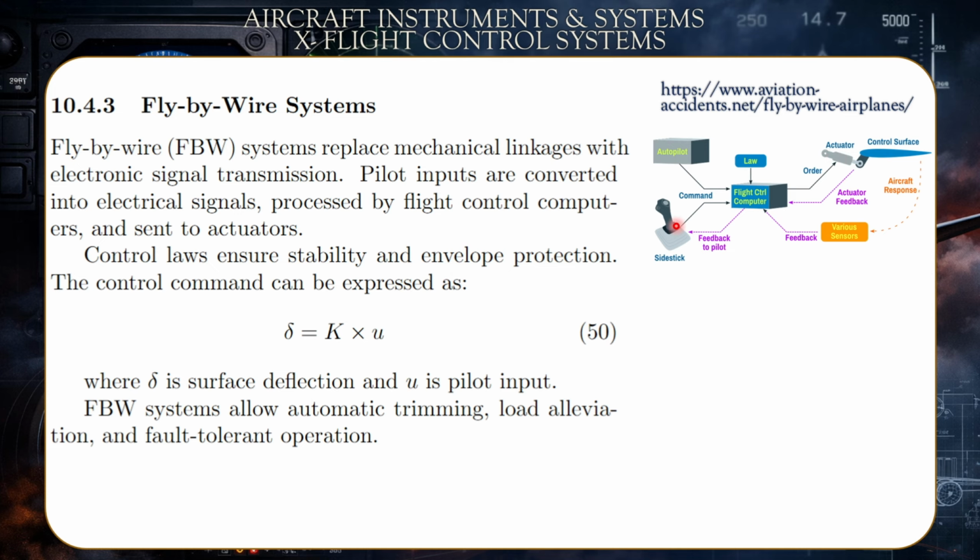So the pilot signal would be processed by the computer as an electronic signal and then replicated to the actuator with the same frequency. It needs to mimic perfectly the action of the pilot himself, except it should be amplified, so as to be capable to move the actuator.